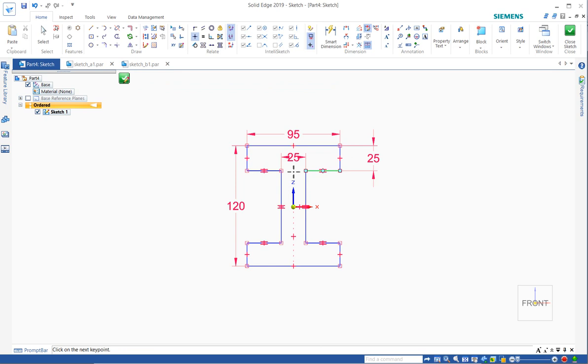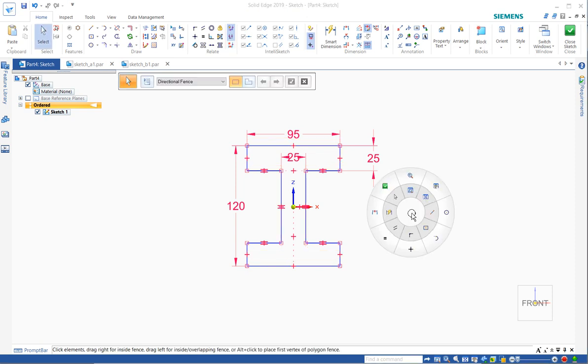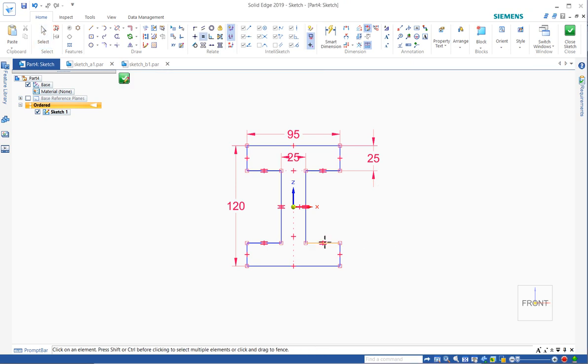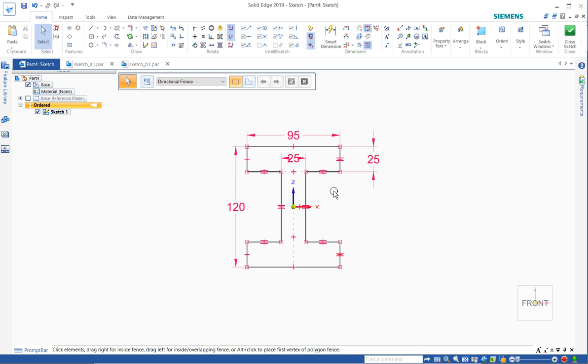So I'll just go and grab probably horizontal, vertical. There's usually 2 or 3 different ways to achieve what you want, and so that should keep it up and down. I got to run it again. This should be a little more obvious, I think, but okay. So the width of the upper and the lower, I forgot to make those equal. Actually, I can see the lack of equal. So see, there's an equal there. There isn't one between here and here. So there we go. That was the last thing that we needed.